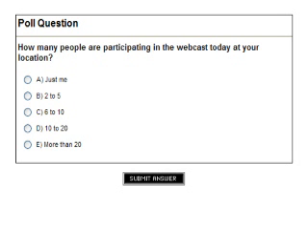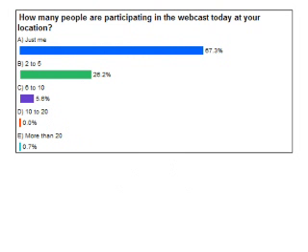Thanks, Mark. Yeah, I wasn't sure if the question had to do with a small footprint for the facility, but the predominant means of disinfection at CSO facilities has been using sodium hypochlorite. So in order to make a sodium hypochlorite disinfection system work, you have to have tankage to store the chemical in and disinfection feed pumps and then some sort of dispersion system, potentially a mixer system to disperse that into the flow.